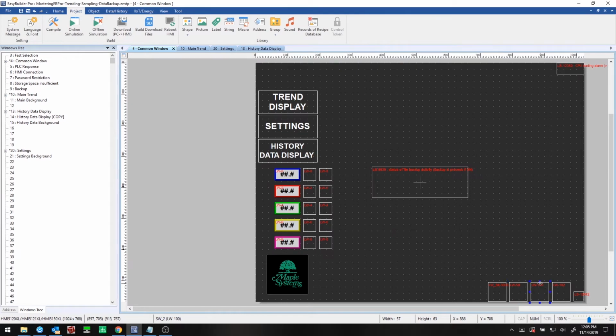And we have setWord objects at local word 100 and local word 102 to set the min and max for each channel to 0 and 100 respectively. All of these objects are set up to write the configuration values on startup when the window opens. An operator wouldn't see these, but they get the trend chart set up properly.